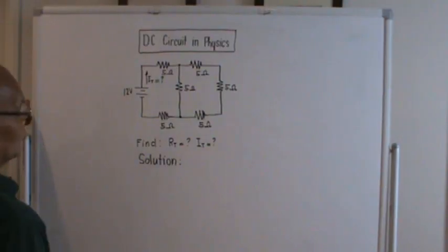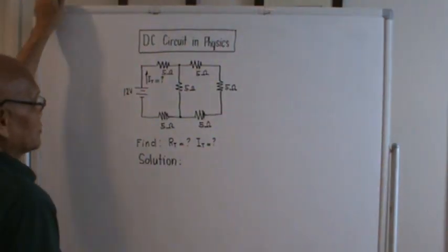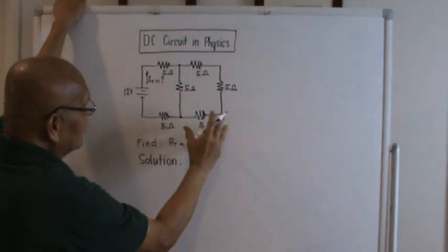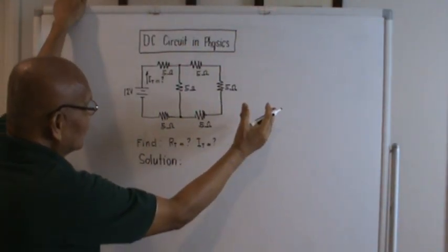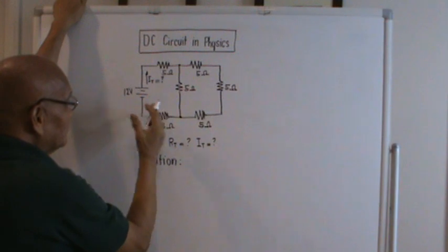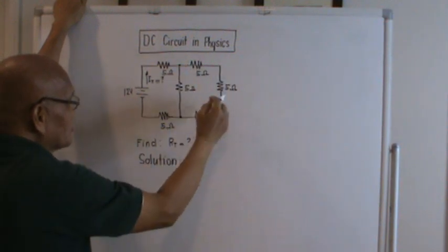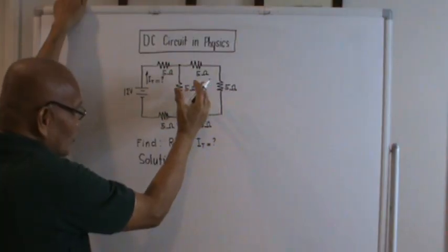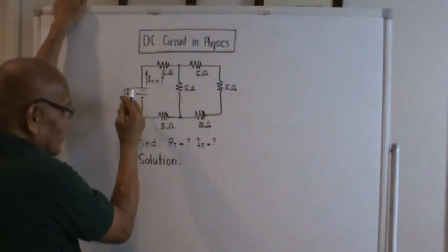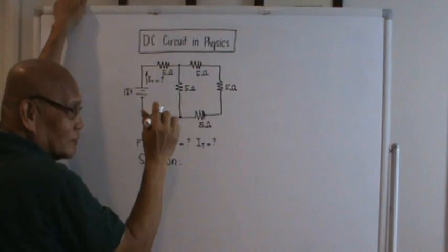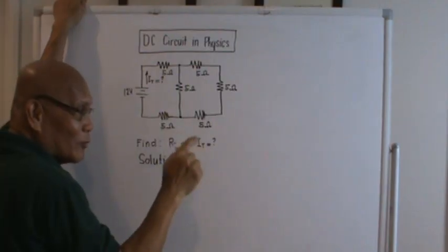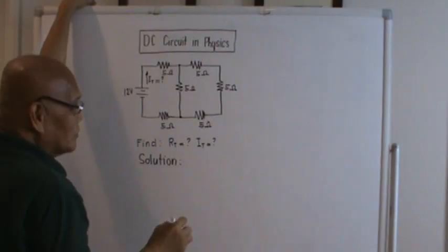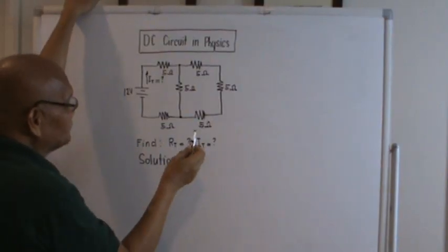Okay, to compute for the total resistance, we must have to start it from the right. Then we'll go to the left gradually, meaning to say we will compress the resistances on the right. Then we try to remove gradually going to the left. Then till come a time that there will only be one resistance left on the circuit. So, okay, let's try to start.